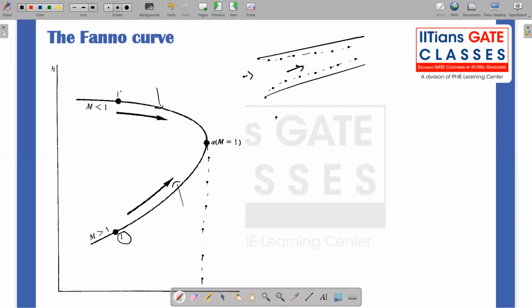After a certain point, it reaches the fully developed condition where the boundary layer thickness becomes constant, so it is no more going to increase. It is not like a flat plate boundary layer scenario; it's a boundary layer within the channel. So it reaches a fully developed state and becomes constant. After that, it acts as a throat, and as a constant area duct afterwards with this throat effective area. There m equal to 1 is reached and it is always going to be the same. So this is just an analogy, okay? It's not exactly how it works, but this development of the boundary layer is always present. So you can understand it this way, as an analogy.